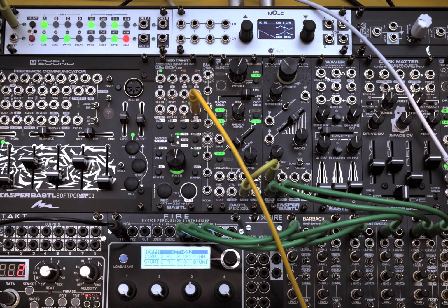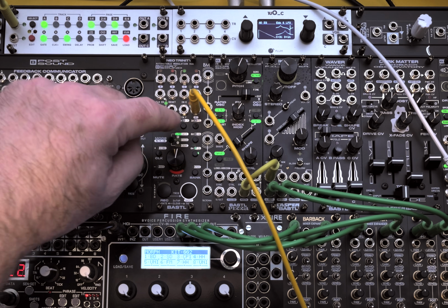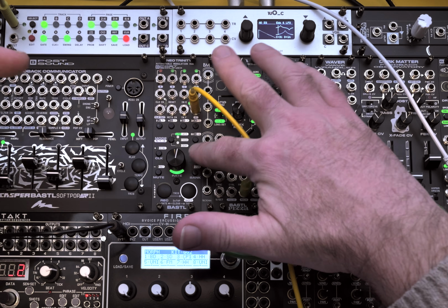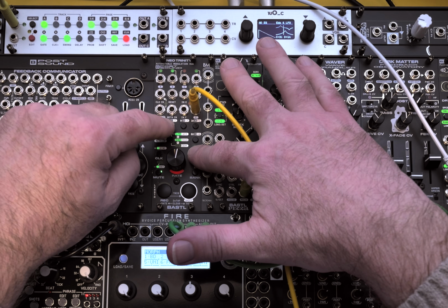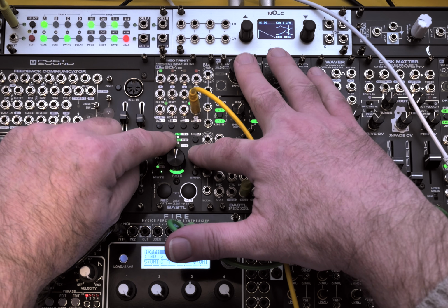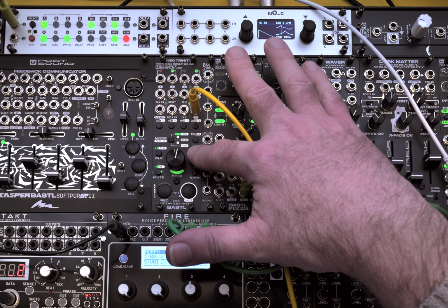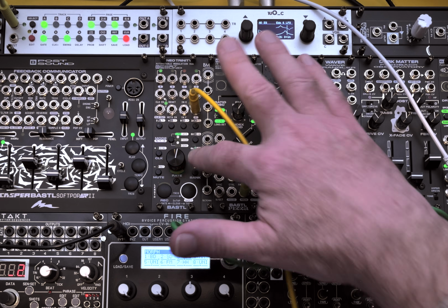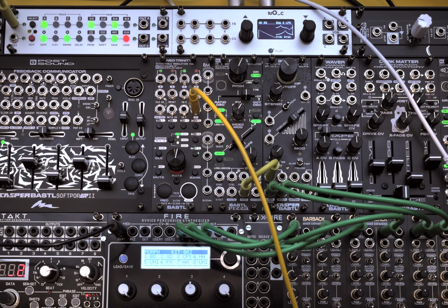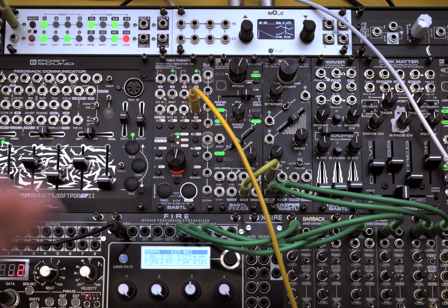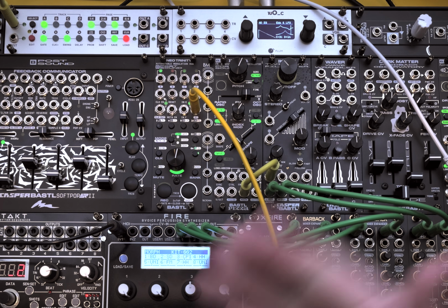So let's go in, and again, you're noticing it's all about changing the modes of these inputs. We press and hold F, and this time we want to change the mode to be the LFO VCA light on. So let's just cycle through till that light is on its own. And now input F allows us to change the amplitude of the LFO signal coming out of channel F.